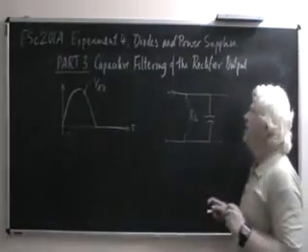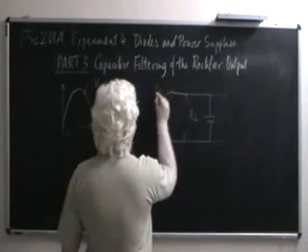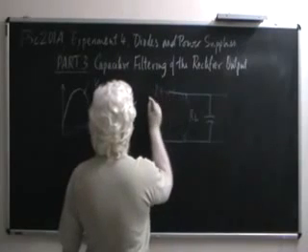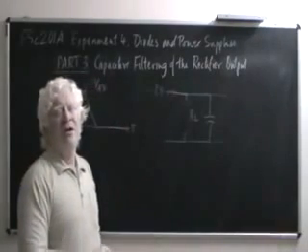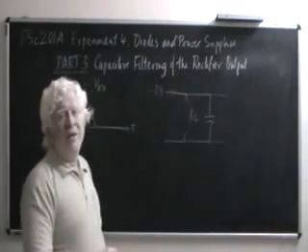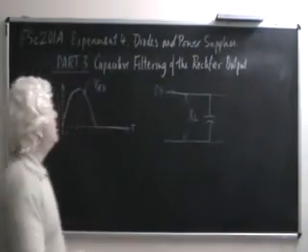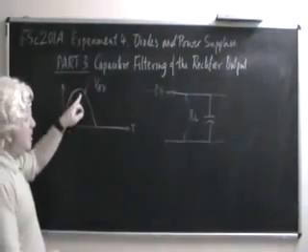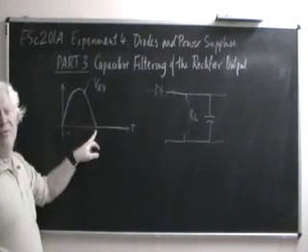Now, let's look at the diode that ought to be here, in the case of a half wave rectifier or a full wave rectifier, it doesn't matter. In the absence of this capacitor, this diode would have continued to conduct until the 180 degree point of the sinusoid.